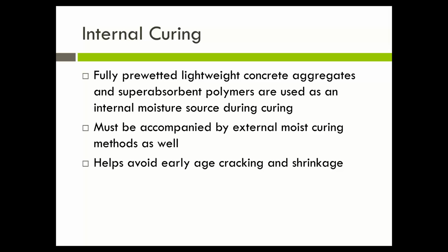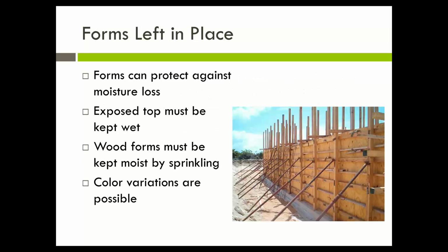It can be quite expensive as well, and it has a detrimental impact on strength because you never get something for nothing. But internal curing is something that you're seeing more and more frequently. Minnesota is using it in bridge decks.